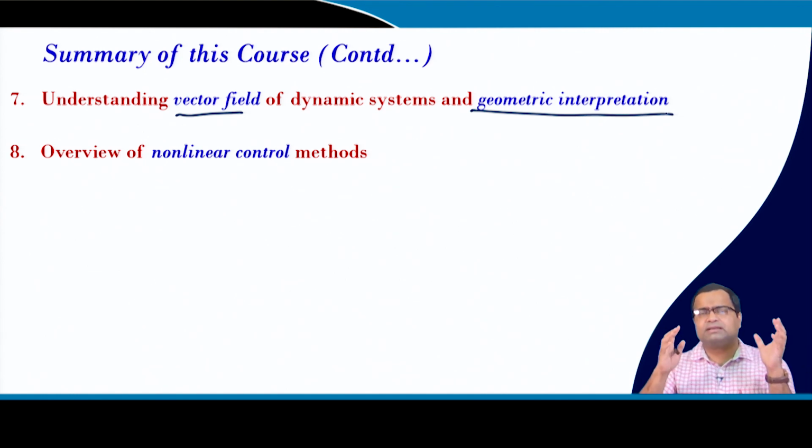And then we have discussed the online tuning, the gain scheduling technique. This can be used to update the parameters to get better response, but again these models, since they are derived based on small perturbation, they do not give enough bandwidth or performance, because there is a model validity concern.